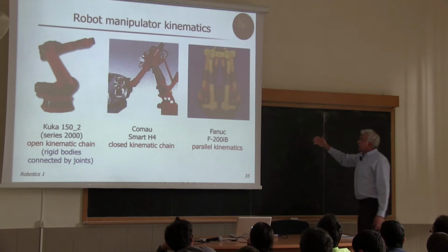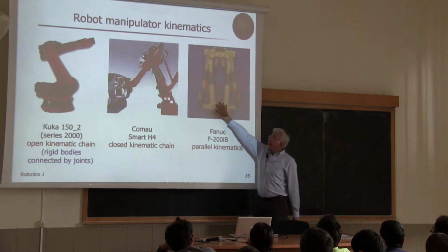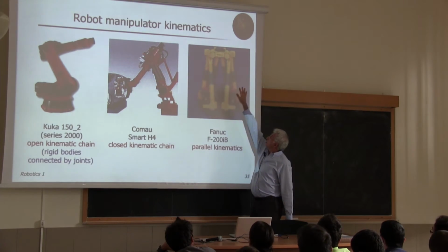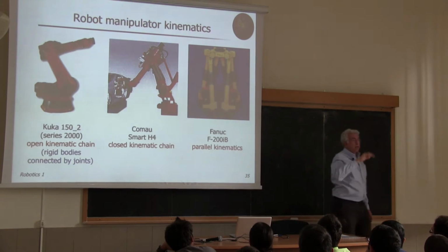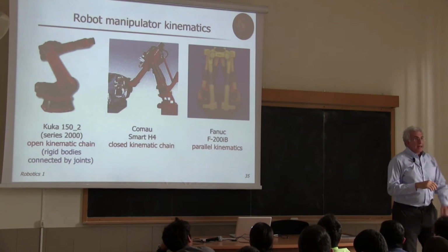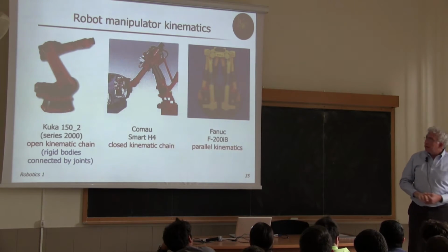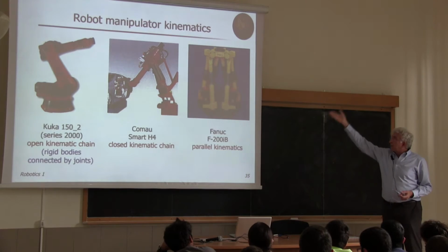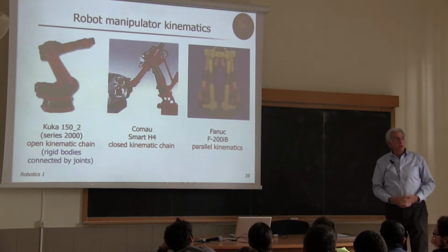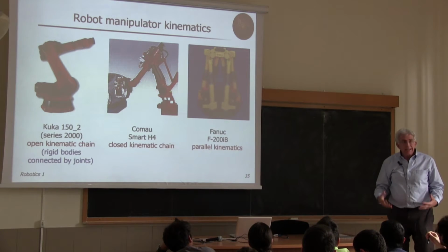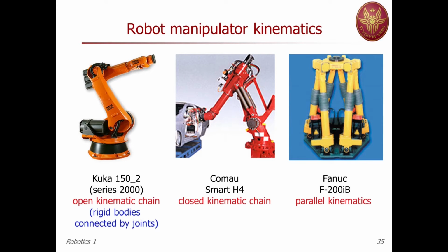By the relative motion of the 6 prismatic joints, the platform which is on top will change position and orientation. As strange as it may seem, the mobility of the top platform, which is the end effector of this robot with parallel kinematics, is exactly equivalent to the mobility of the end effector of the 6 degrees of freedom serial manipulator that you see on the left.